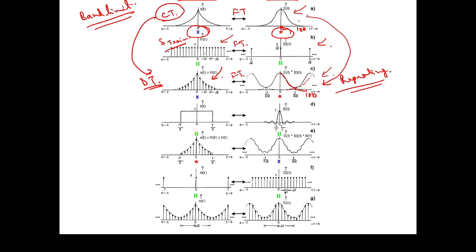Okay, now why is it done? This is because of a criterion which is regarded as the Nyquist criterion, which says that the sampling frequency should be greater than or equal to 2 times the maximum frequency. And as I told you, any continuous time signal has an infinite number of sinusoidal signals.